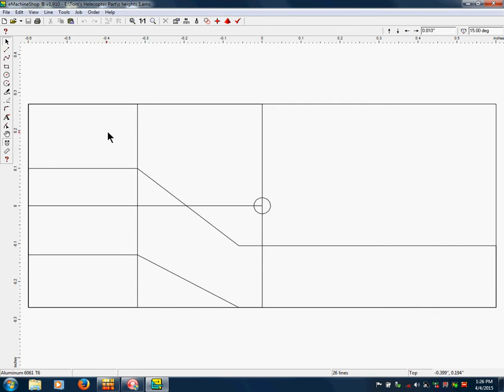Now, I cut originally when it was flipped over the other way from here to here, somewhere in this area here. Imagine the cutter coming from the bottom up because the part would have been flipped over. Now to release the part, I have to cut from here down to here. Okay. I can actually set that depth.